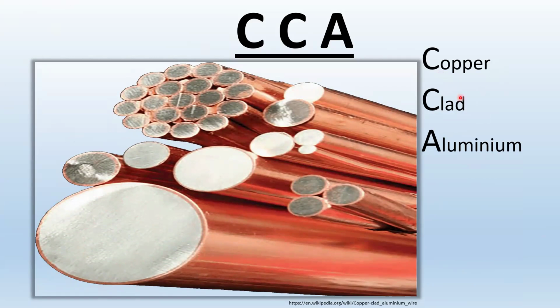Those cables, those data cables or any other cables, when it says CCA, they're about 3 times cheaper than the BC, which is bare copper, which is the whole wire is copper. Even though it's 3 times cheaper, do not buy that CCA. You see the CCA, you run from it as far as you can get. It only causes trouble. That's all I can say. Do not be tempted because the price is good. Make sure if the price can be good, just make sure it's not CCA.